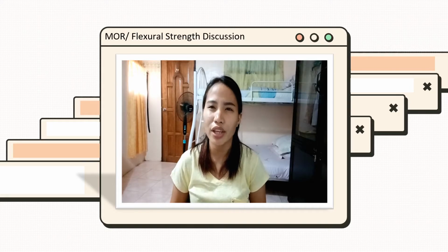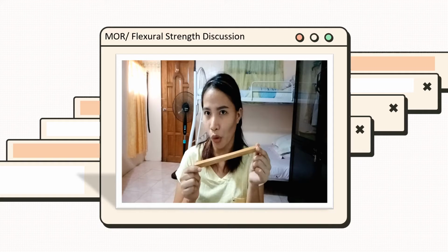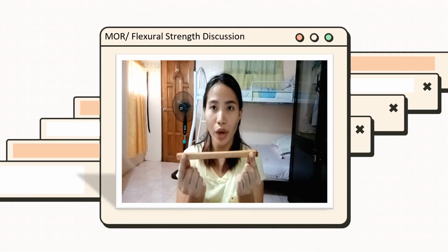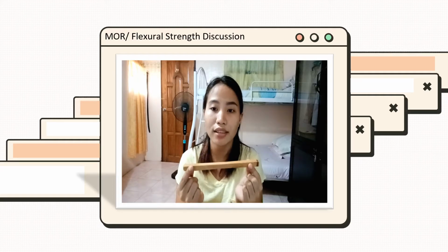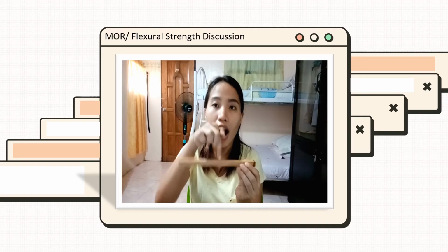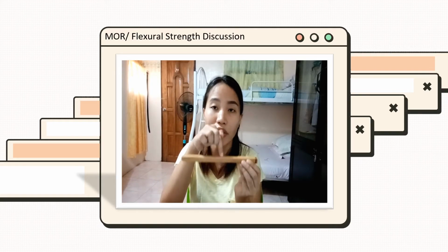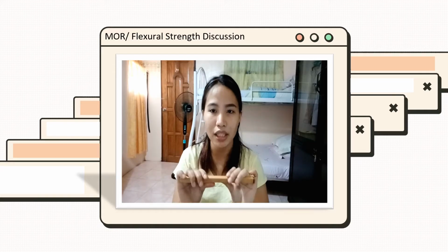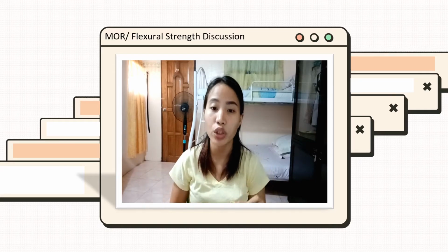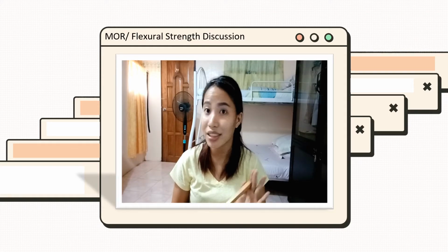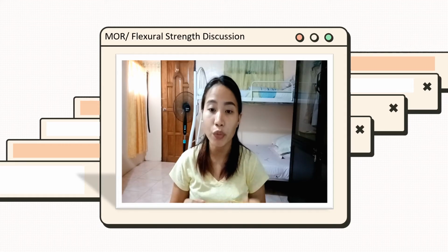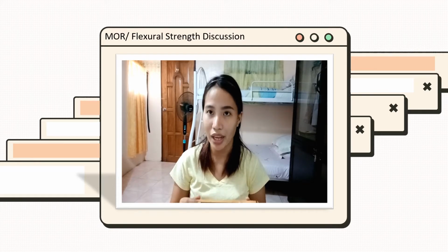If this is difficult to get your head around, think about a plank of wood like this one, supported at two ends. If you want to know how strong the wood is, one way to test it would be to push down harder and harder at the center of the plank until it snapped. The maximum pushing force the wood could withstand before breaking is its flexural strength. If another piece of wood was stronger, it would support a greater force before breaking.